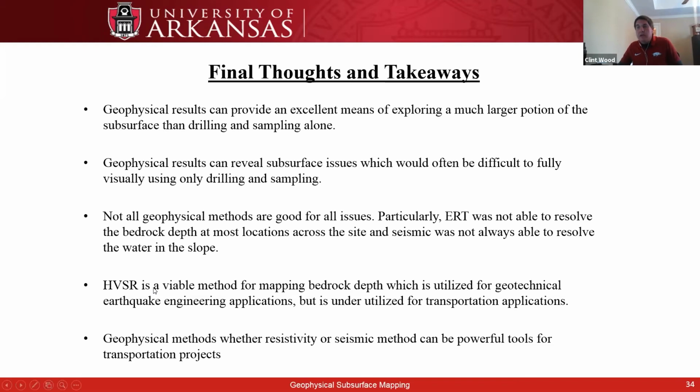And then HVSR, or HRV, is a very viable method for mapping bedrock depth, which we've utilized for decades in the earthquake engineering application world, but it's often underestimated or underutilized for transportation applications. And although it's not part of AGaME, we still use it a lot. I know other people have started using it. Hager-Richter was one that used it in the last session that we talked about for AGaME.